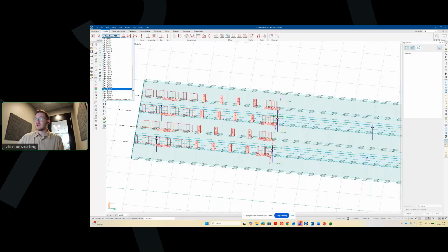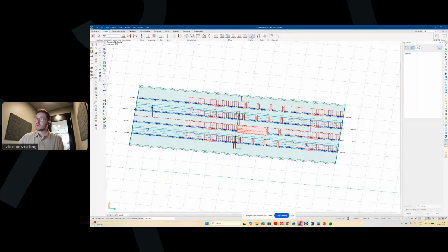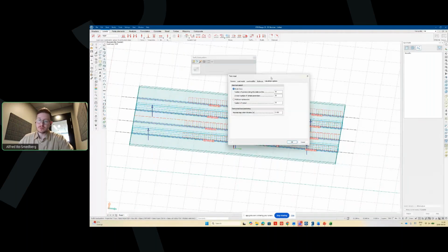But for the sensitivity analysis for traffic loads, we have, for example, in the calculation options, the choice of the search algorithm type as well as the number of positions or restarts that are used during evaluation. This can have a huge effect on the level of detail and on the time. So let's do some testing with this one soon.